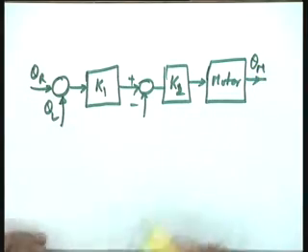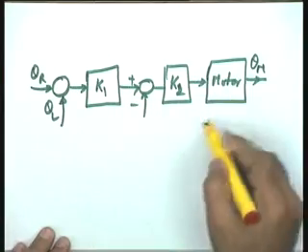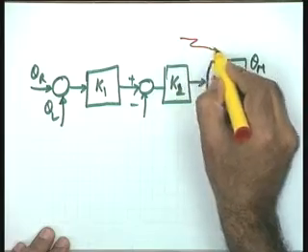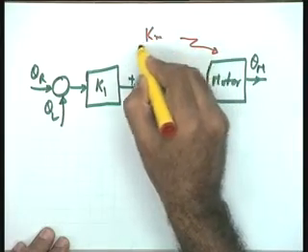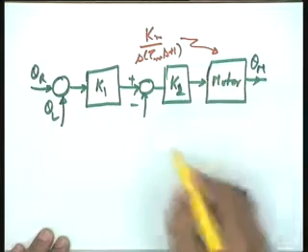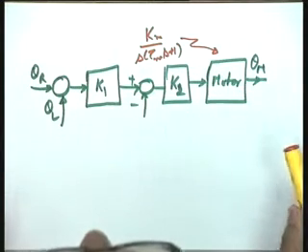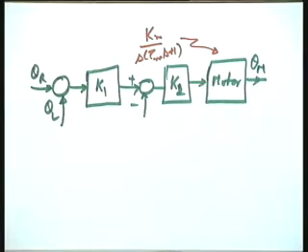The motor relationship you will be able to draw, and you know that the transfer function of the motor is Km divided by S into tau m S plus 1. You can complete this block diagram through the feedback loop, which is the back EMF loop. I am not taking that, I am taking this as a motor.